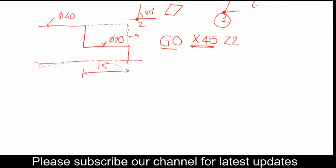So yes, now what does this mean? G0 means rapid interpolation. For this machine, the rapid rate is 24,000 mm per minute.